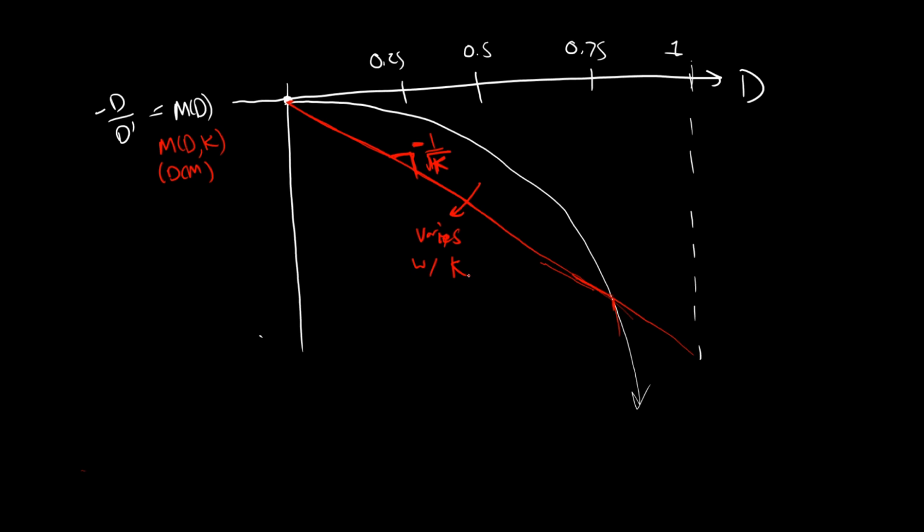So maybe I'll do a tutorial version of this where we'll just grind through more specifically with a 2-inductor converter, and we'll see that the condition between DCM and CCM looks a little bit different, because we're looking at when the diode current tries to go negative.